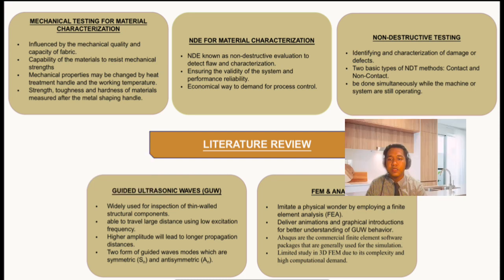Next is guided ultrasonic wave. Guided ultrasonic wave is an NDT that is widely used in inspection of thin wall structure components. It is widely used due to its advantage of being able to travel a large distance using a low excitation frequency.